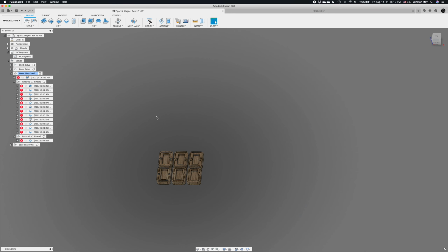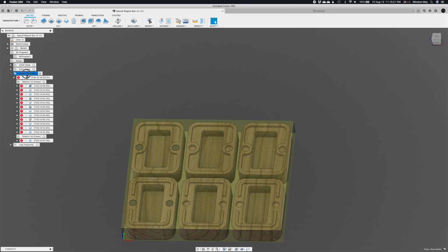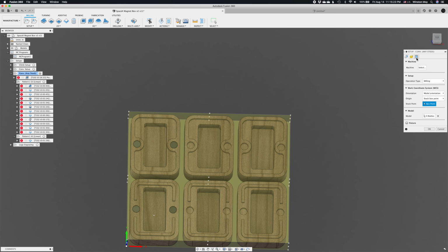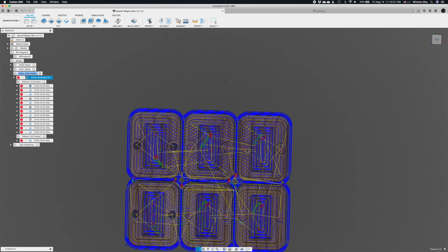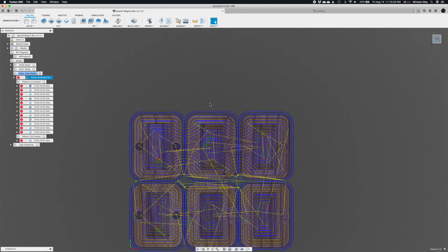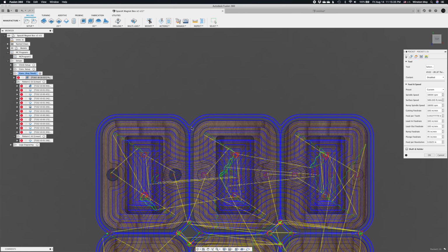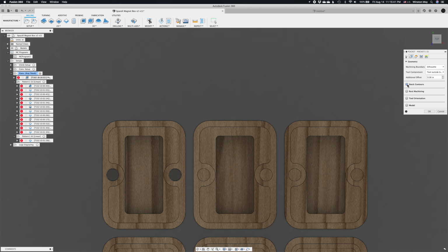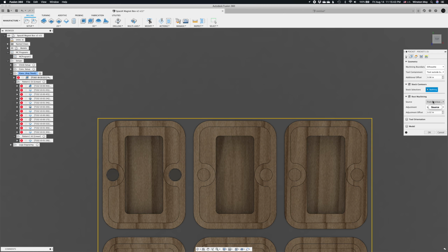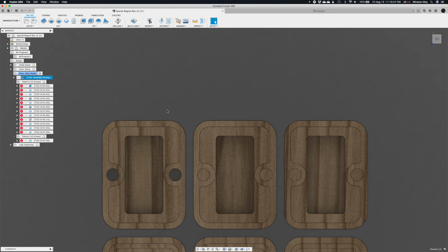There's a couple ways you can do this. If you have a perfectly sized piece of stock that is 5.375 inches wide and 4.5 inches long, you can create a pocketing toolpath that will just sort of dip into the areas it needs to cut and ignore the rest. So if I have stock contour selected and rest machining from stock setup, the toolpath will look a little different.